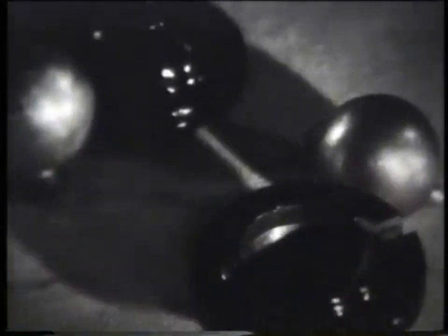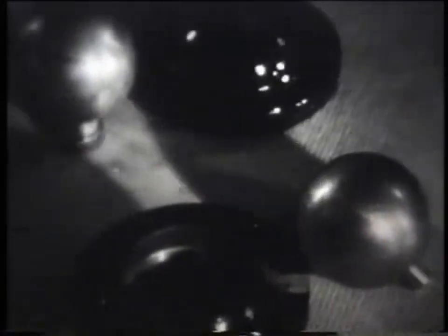In fifth class pairs, contact between the links occurs on a surface. In rotational and cylindrical kinematic pairs, this is a cylindrical surface. In the translational pair, a plane. In spherical and spherical with a finger kinematic pairs, the contact between the links is carried out on a spherical surface. Kinematic pairs in which the contact between the links occurs on a surface are called lower kinematic pairs.